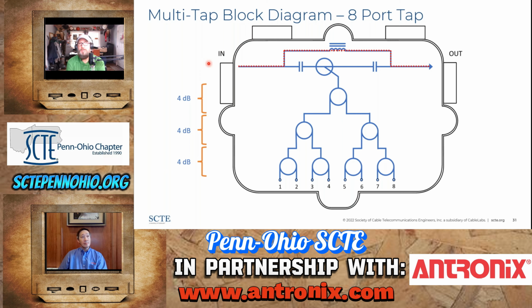So there is a possibility in this instance, if this were a 20 dB tap, and let's say that the tap itself was broken or damaged, but the only thing that you had was, let's say, maybe an 11 tap. If you were to put an 11 value tap in a 20 value tap's place, the insertion loss is going to be different, and that'll have consequences for the subscribers farther down the line. Correct. Because you can't create power, it's split.